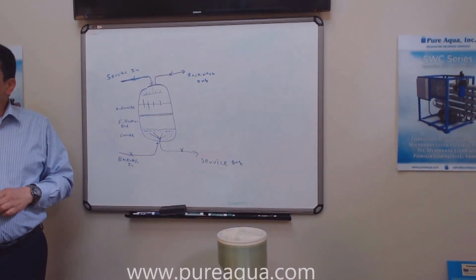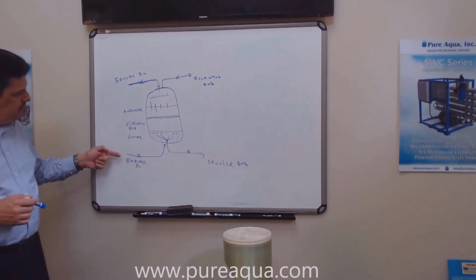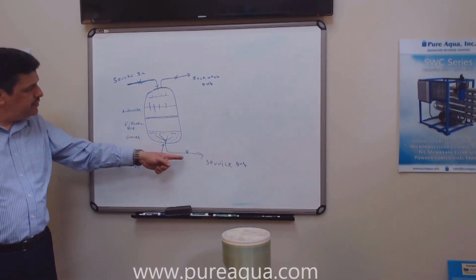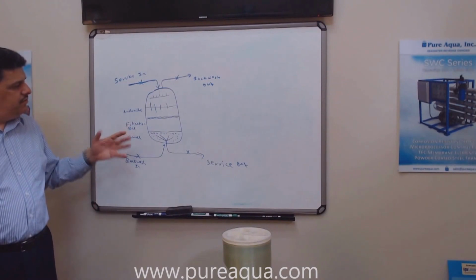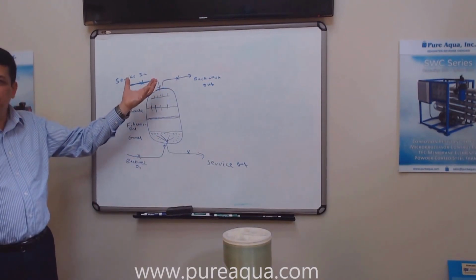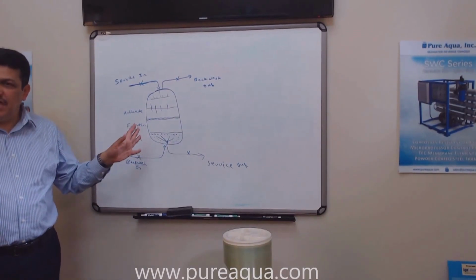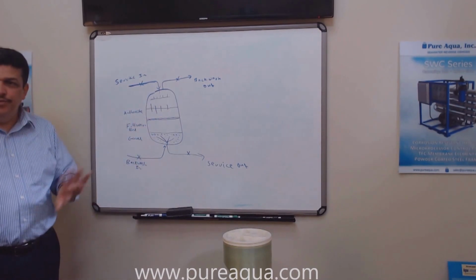The rinse process is the one that happens after the backwash. That means when you're doing the backwash, the water is going to come from here. So this is closed, this is closed, this is open. So everything is going reversed. So now it's time, the tank is clean. So we're going to put it back to service. No, we don't want to put it back yet.